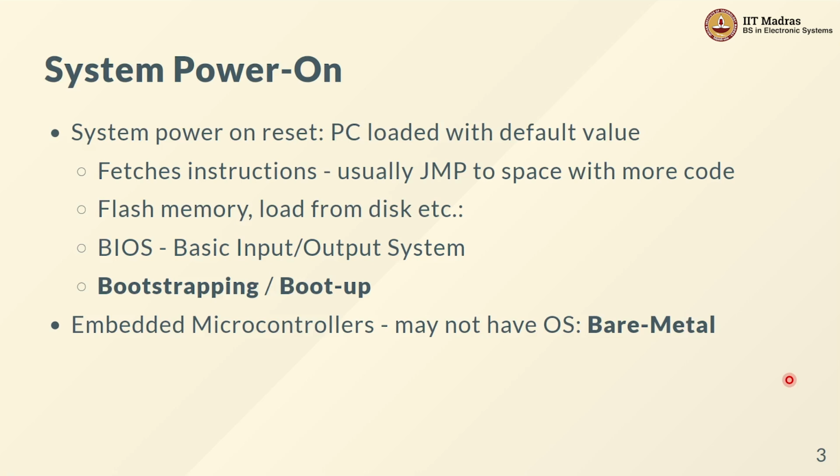Now, let's think about what happens the moment that the program counter has got a value, and then the clock starts ticking, right? You get positive edges on the clock. From our understanding of how a CPU works, we know that it will start fetching instructions from the instruction memory, at the address corresponding to PC.